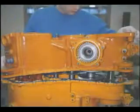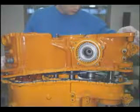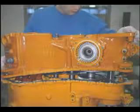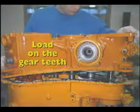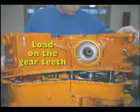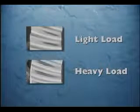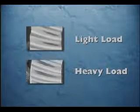When a gear is installed in a gearbox and is actually powering the designated application, there are varying degrees of pressure or load on the gear teeth. When the gear teeth are under load, the contact pattern will change. Here we see a contact pattern from a gear with a very light load. And here is a contact pattern from the same gear with a very heavy load. So there is a general rule of thumb which states that the heavier the load, the larger the contact pattern.